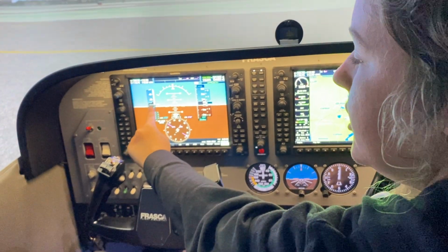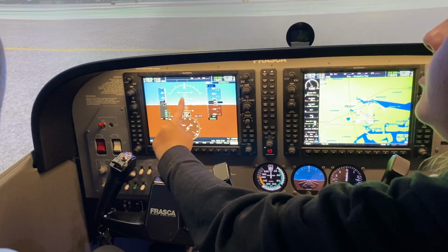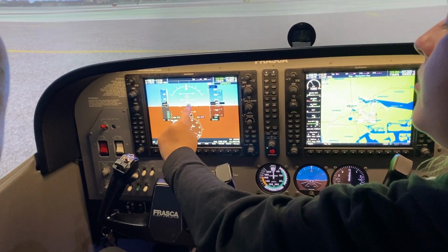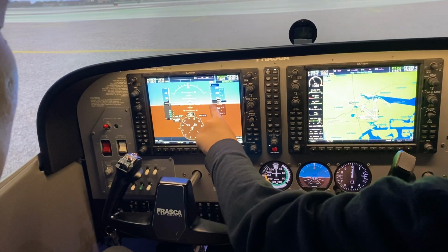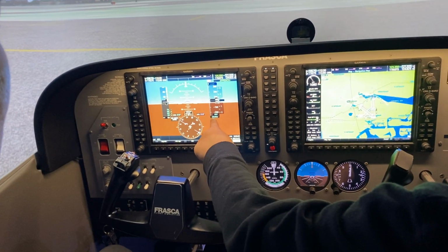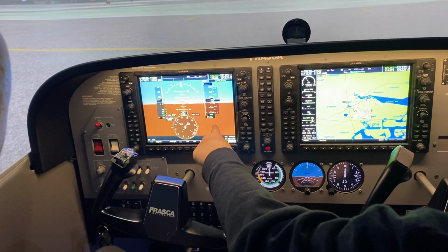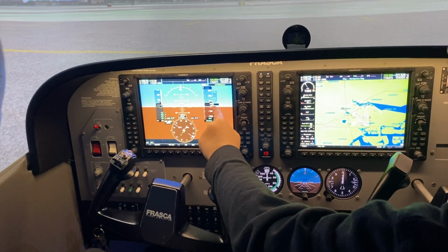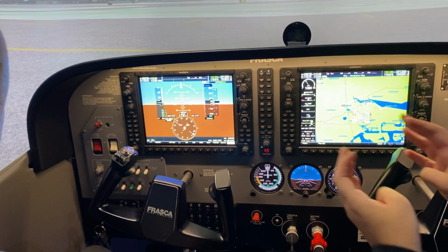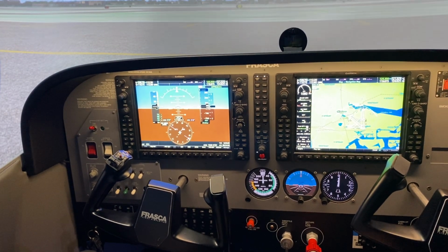Airspeed, we're checking to make sure it's at 0. Our attitude indicator, we're checking to make sure is level, blue above, brown below, and it's not up here at like 10 degrees. It's just a little bit above the horizon. Then we're checking to make sure our altimeter is set to the correct setting, which we would hear from the ATIS, which we have gotten before this. Okay. And we would check that the altitude it's showing is plus or minus 75 feet in regards to our field elevation.